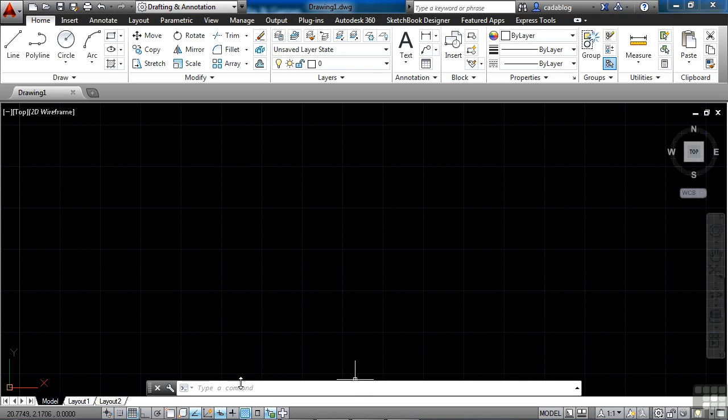If you look at the bottom middle of your screen, you will see a gray area, one line like this. And as you move the mouse over the top of it, move your crosshairs, it will highlight. This is the command line. Even if you don't use keyboard input, you are going to use the command line. AutoCAD will give you instructions on what to do next while using each of your commands, and those instructions will be brought to you by the command line.